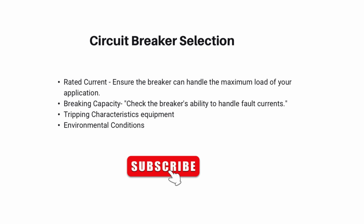How do you choose the right circuit breaker for your control panel design? Here are a few key factors to consider. Number one, the rated current. Ensure the breaker can handle the maximum load of your application.